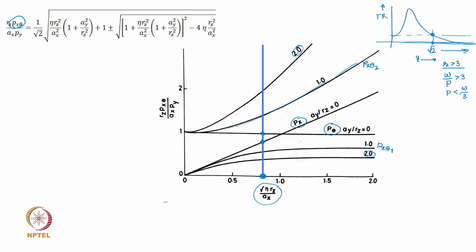When we were discussing transmissibility in a single degree of freedom system, what we also looked at is that if omegas are multiple in number, 1 omega, 2 omega, 3 omega, higher harmonics of omega, if you design it for lower omega, it is fit for all other higher omegas. Okay, now here the condition is different. You have multiple p's, you have many natural frequencies to account for a single omega. In this particular case, assume that there are no higher harmonics of the excitation frequency.